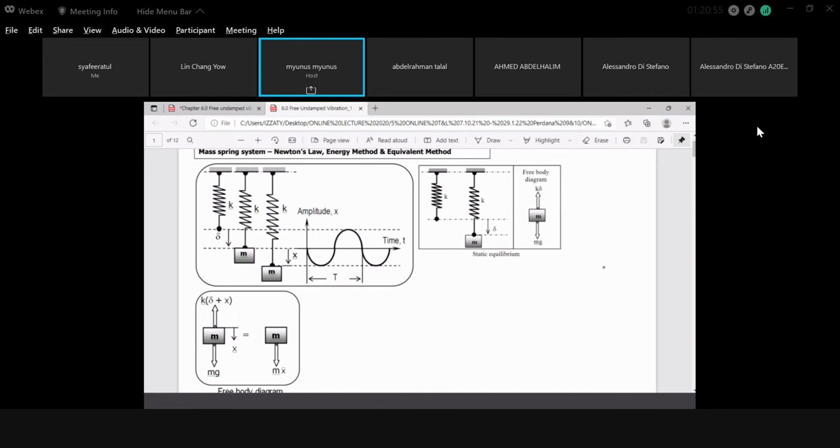Okay, now look at this. This is the first one from just now. There's no displacement because the spring is at its own position, at rest. Spring at rest, there is no deflection yet. Then you put mass here, then we have this delta. This delta we call static displacement, isn't it? Then you displace m, then you let it go. So it oscillates, creating simple harmonic motion. This one we call simple harmonic motion.